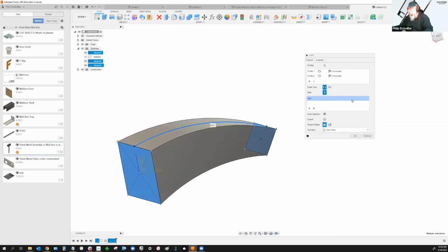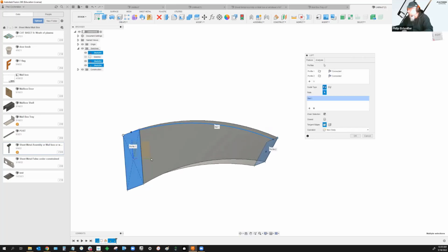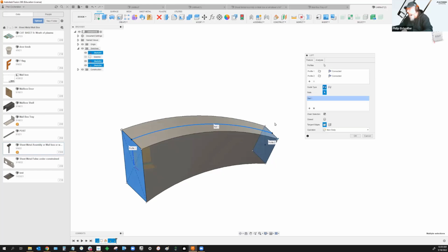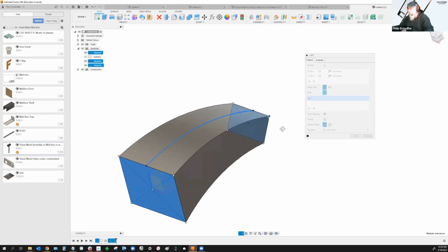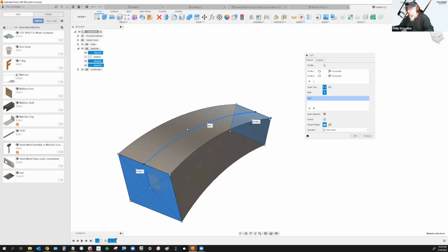This is really similar to that direction, the way it looks when you pick direction. But notice how it's nice and smooth. It's not bothered with takeoff and curving and waving as it comes in and out of the shapes. It's just very literally following that rail. So you can add any number of rails, and usually people are probably using 3D sketches to do that.